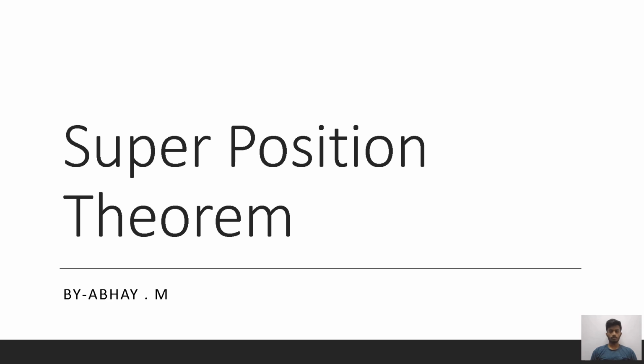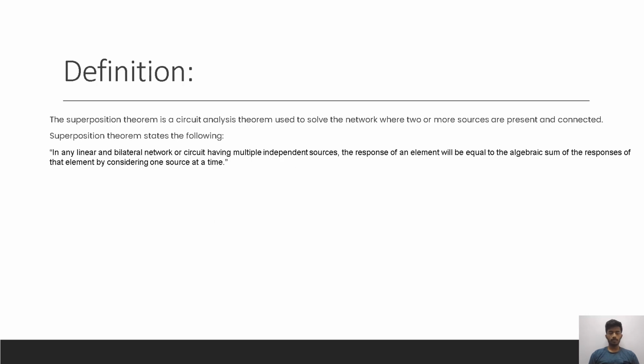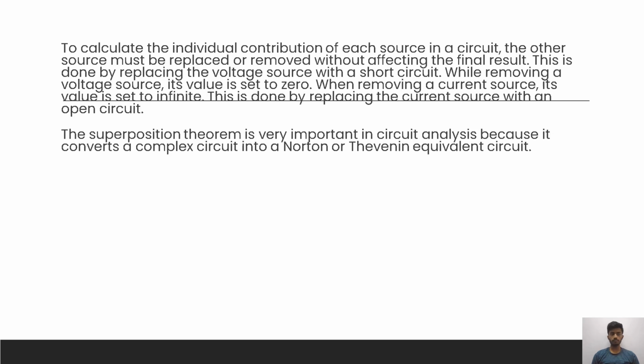Today I'm going to discuss the superposition theorem. Definition: the superposition theorem is a circuit analysis theorem used to solve a network where two or more sources are present and connected. Superposition theorem states the following: in any linear and bilateral network or circuit having multiple independent sources, the response of an element will be equal to the algebraic sum of the responses of that element by considering one source at a time.